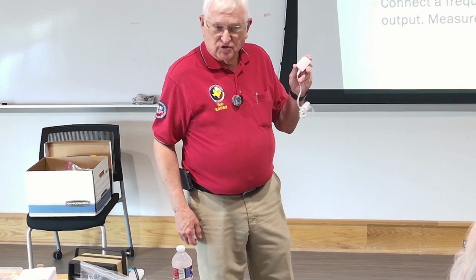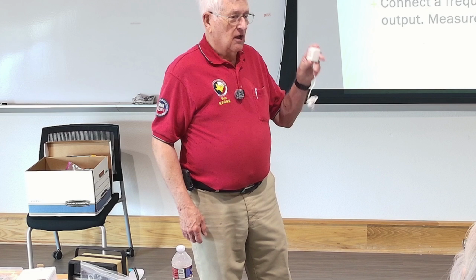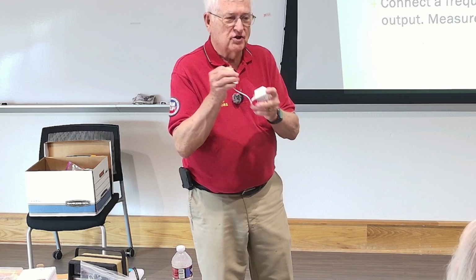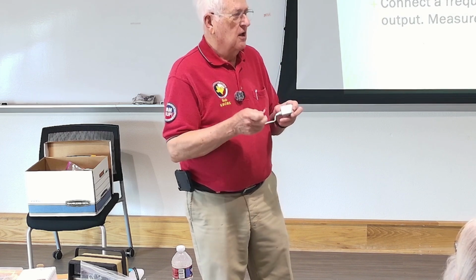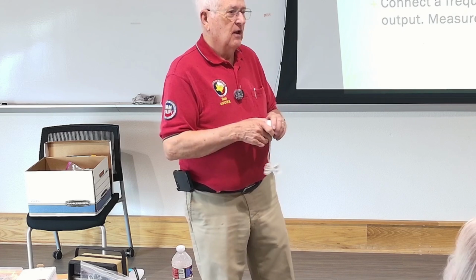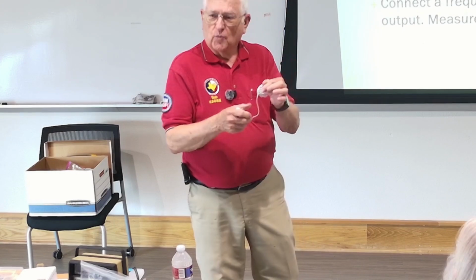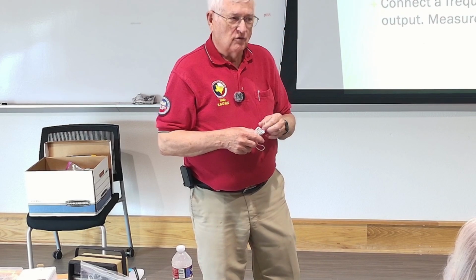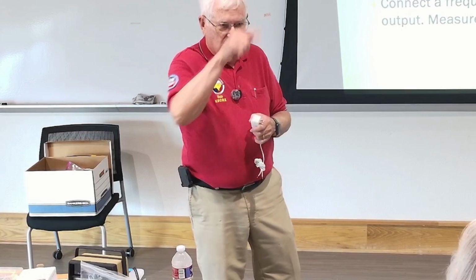The real reason is it's low voltage, low amperage. You're not going to get shocked or hurt off of that. Coming out of those two little wires, you should see pure 60 cycle AC, or 60 hertz AC. When you can, there are enough outlets over there, plug that little guy in, hook it up to the scope probes, and see if you can read the voltage that we have coming into the house. Through that, you should be able to see peak to peak and measure it.